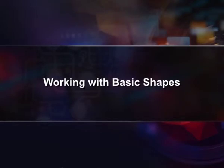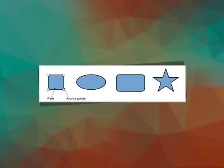Working with basic shapes. Illustrator offers a large variety of shapes such as rectangles, ellipses, rounded rectangles, polygons and more. A shape you create is composed of anchor points with paths connecting the anchor points. A basic square, for instance, is composed of 4 anchor points on the corners with the paths connecting the anchor points. See the figure at right.